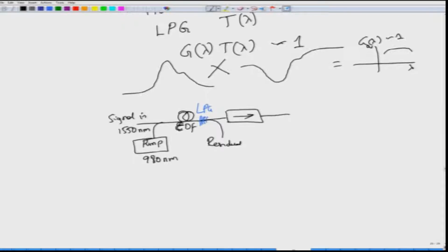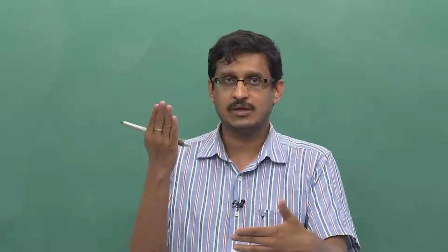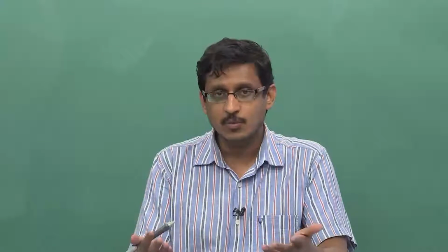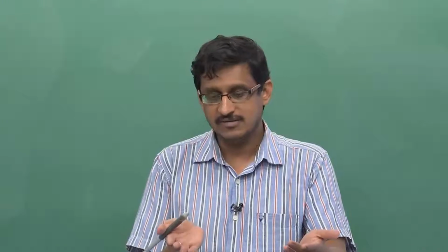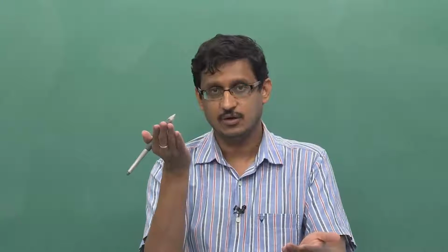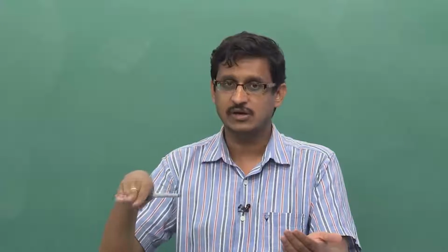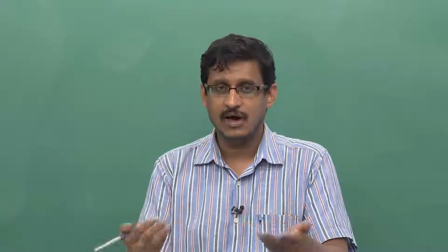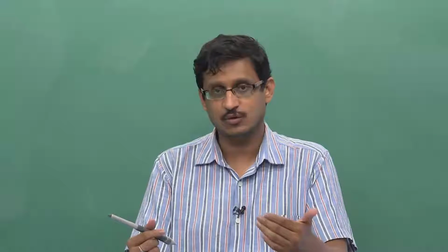There are a couple of things on which the gain depends. We have already seen that the gain increases with the pump power that is input. However, is it possible that I can just keep on increasing the pump power so that the gain keeps on increasing? Unfortunately no. The reason is that a larger number of pump photons coming in means that these ions are getting excited, however they will also start to decay back. So there is some sort of saturation that happens when you start putting in a large amount of pump power. This saturation is even more pronounced when you actually have a signal.